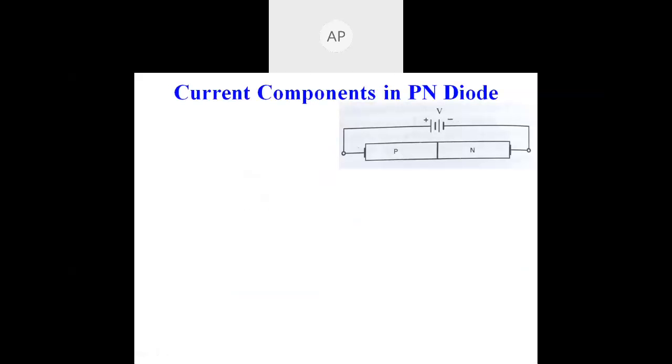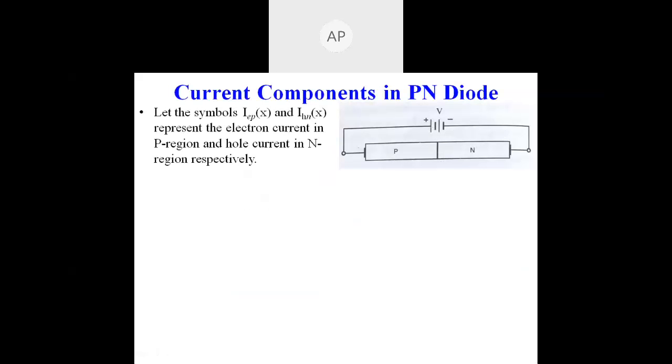You will have this characteristic curve for the germanium material and the silicon material. The forward current is linearly rising, and the reverse current is slowly increasing at a constant rate. So these are the ideal characteristics.